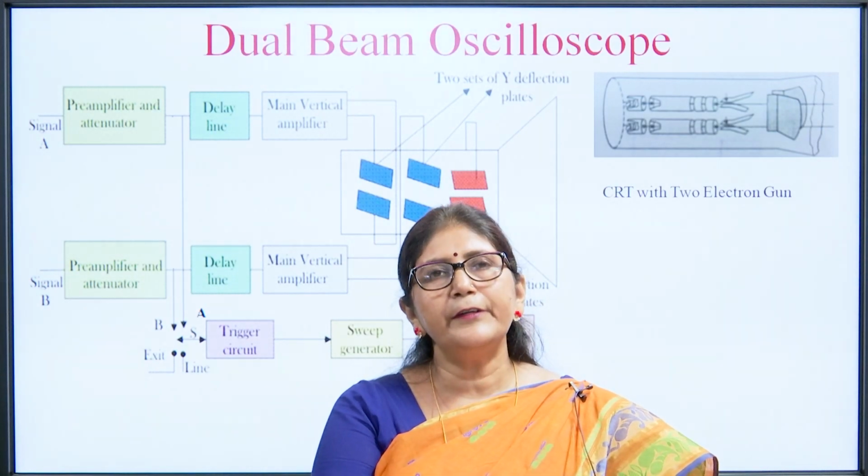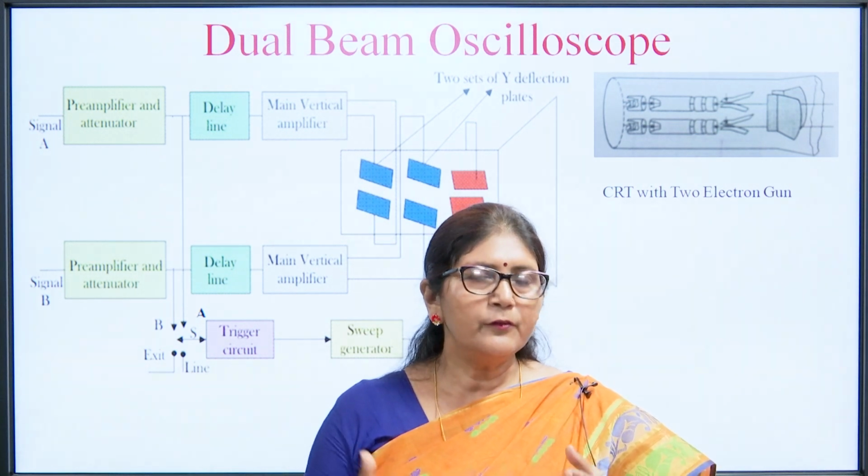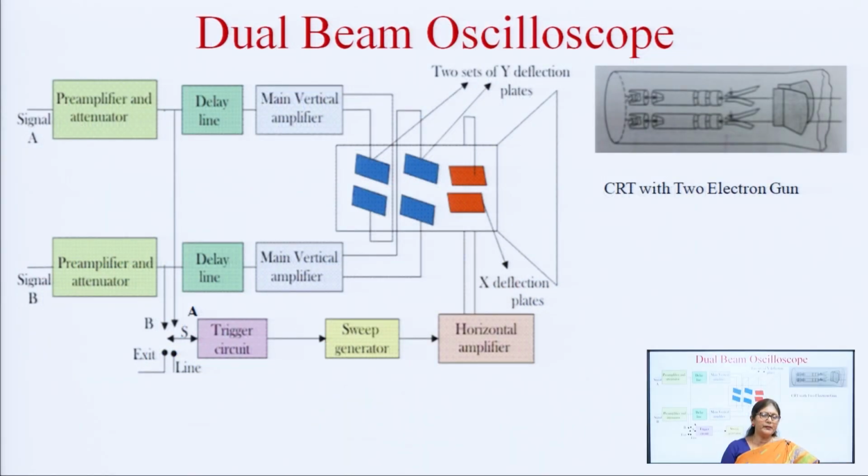As we can see in the figure, suppose we want to analyze two signals simultaneously. Suppose we have designed an amplifier for a gain of 5, then we want to see whether it is producing the gain of 5 or not, and we want to analyze whether the output is an exact replica of the input or not. So, we need a CRO that can measure two waveforms.